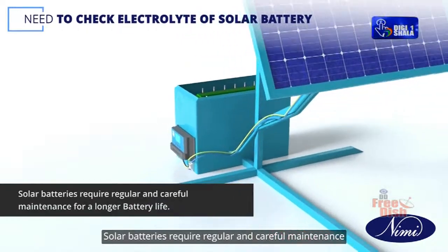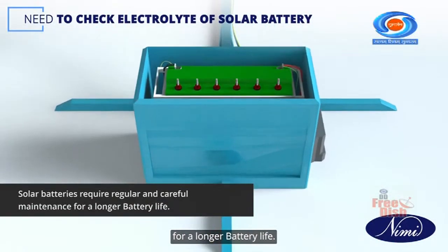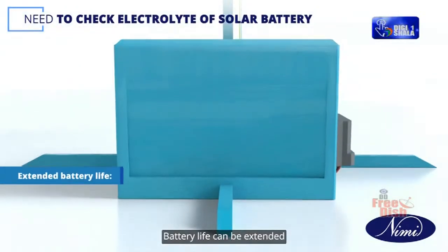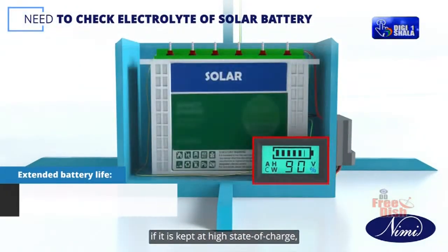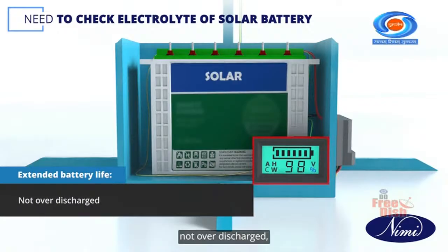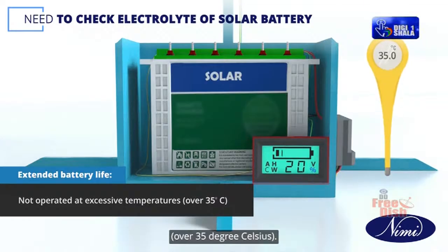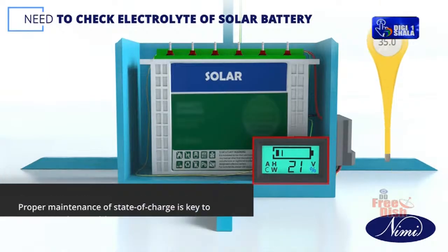Solar batteries require regular and careful maintenance for a longer battery life. Battery life can be extended if it is kept at a high state of charge, not over-discharged, or operated at excessive temperatures over 35 degrees Celsius.